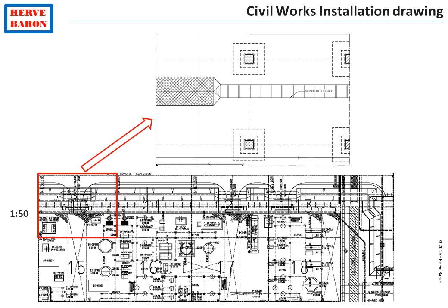The following revision will be the sewage branches and the firewater branches that come just on top of the headers. The following revision will see the cable trenches which come on top of these pipe networks. Finally, the last revision will show all the surface elements such as cable sleeves, pipe support foundations, small process drain lines, and so on. The cinematic that follows will show you the growth of the contents of one civil area drawing over its various revisions.